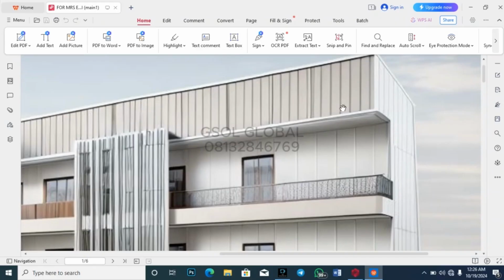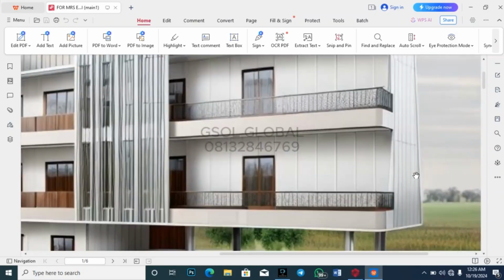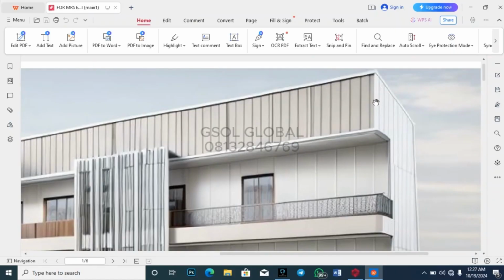Even if you're not having a short wall, all these elements above this particular beam are load on the beam. So you have to ensure that you load the beam. Even if I'm sure it's a very short wall that is on that particular beam on this roof layout beams. All right. So it's a short wall. So we're going to go ahead and place short walls on all the roof layout beams to ensure that the roof layout beams are loaded, so that it will give us an equivalent design that will be able to withstand the equivalent load we see right here.